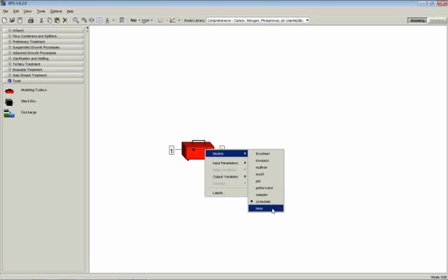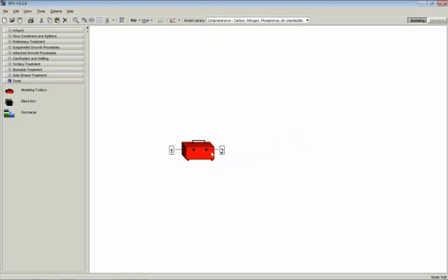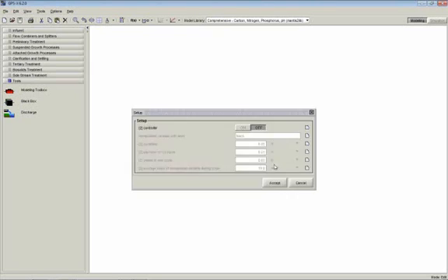I will also briefly mention our new flow timer. So you may have used the timer in the past where you specified an overall cycle time, and then you said I want a value to be on for 2 hours at some value, and then I want it to be off for 3 hours and set it to 0. This is more or less the same kind of thing. You specify your overall cycle time and how long you want it to be on during that time. But rather than specifying the on values and the off values, you specify the range of manipulated variables, or what you would like that average to be over that cycle.